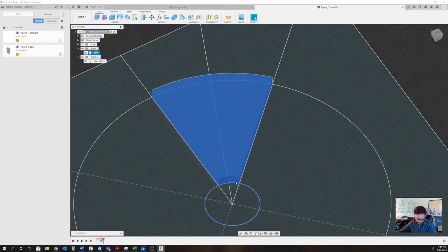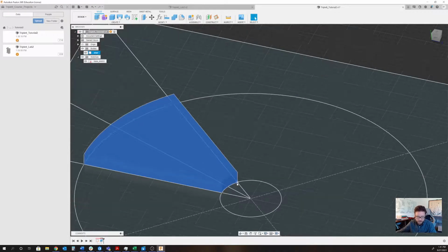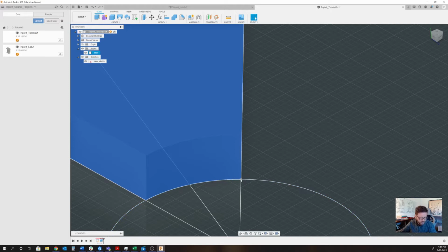You're going to notice that with these bodies, it turns your base sketch off initially, so you might want to turn that back on. And the first thing I want to do, and this is a little bit confusing because it didn't used to work this way, is that you need to project anything that you want to snap to. After you've created your planes, in order to draw and snap directly to things that are not on the same sketch that you're on, you need to project them.